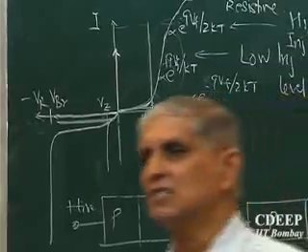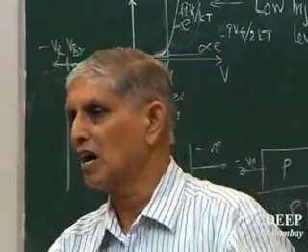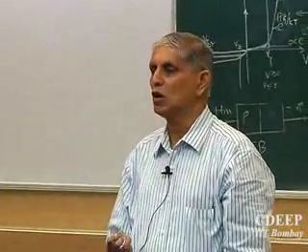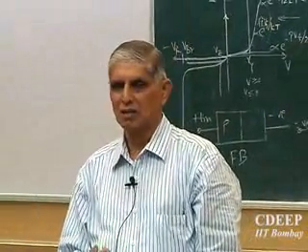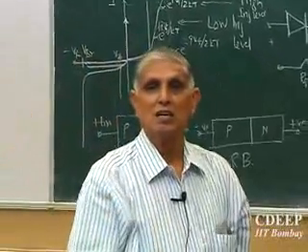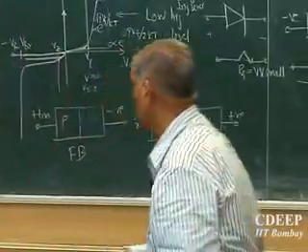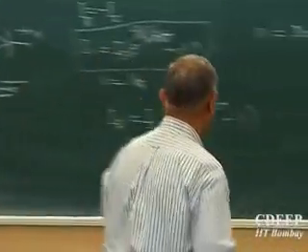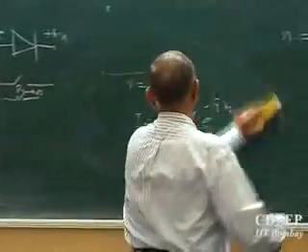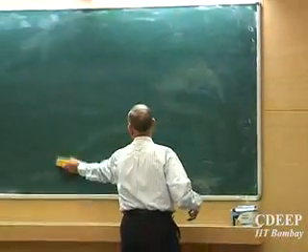So there is a mechanism of failure or breaking down at very low voltage of a PN junction in the reverse bias called Zener breakdown. The one which is larger, shown as VBR, is because of the phenomenon called avalanche breakdown. So we will also see the breakdown characteristics of a diode.